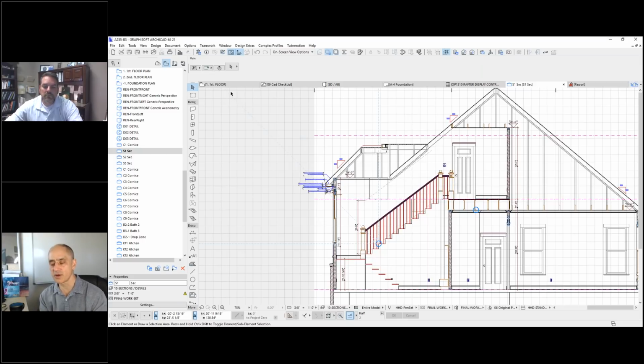CAD Image does make a very powerful wall framing tool for people who do want to do wall framing diagrams or drawings and counts. But one trick I've seen is sometimes people will use the roof tool for slabs because you can just make it literally zero slope, and then you can use the Roof Wizard. So I haven't seen it done often, but I've heard people say that it can work okay.